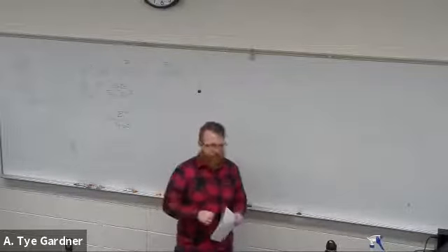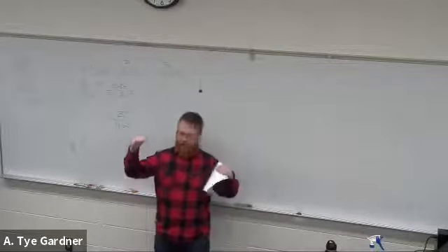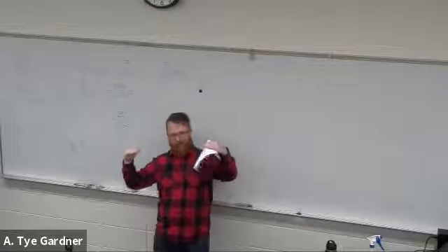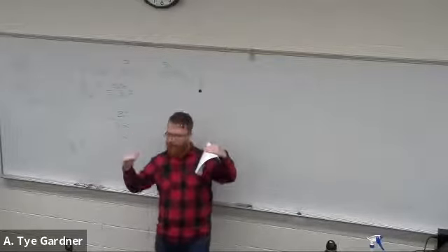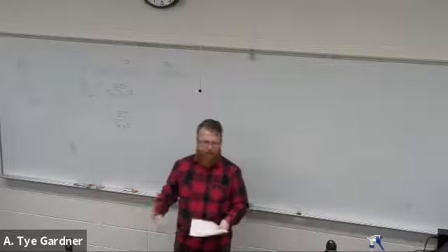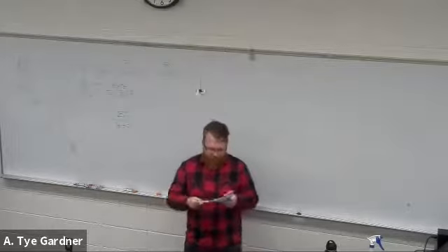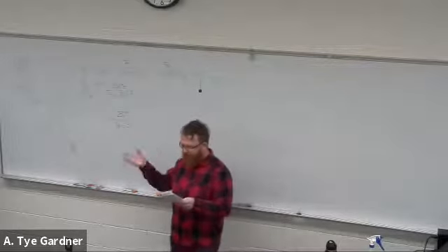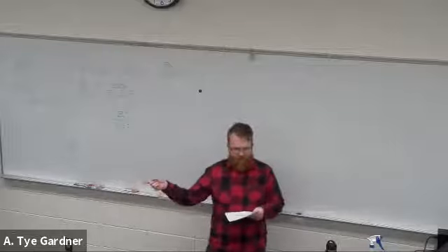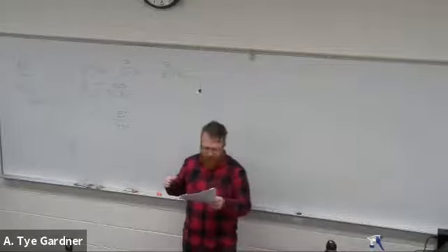The obvious one is you build a scale, right? A balance that you put something on here, you put something else here, and you see how far the scale moves. That's the simplest one. We don't really use that as a sensor because the output isn't electric, so it's not really helpful. The other way is we want to measure the acceleration of a known mass. So if we know the mass, measure the acceleration, we know force, right?